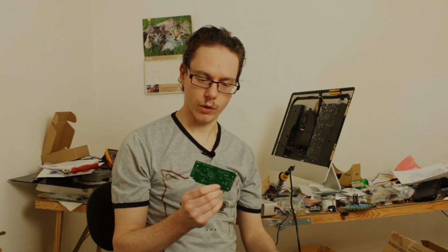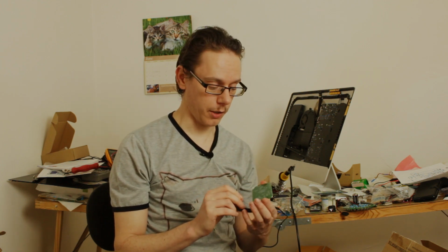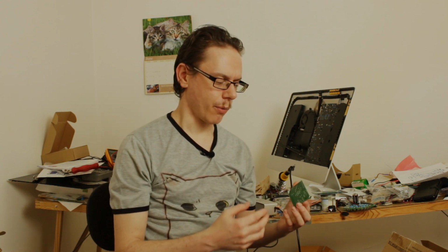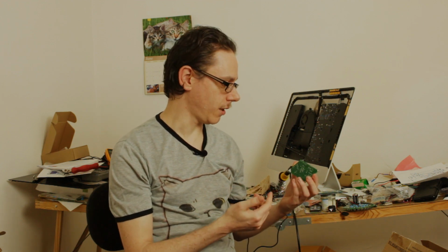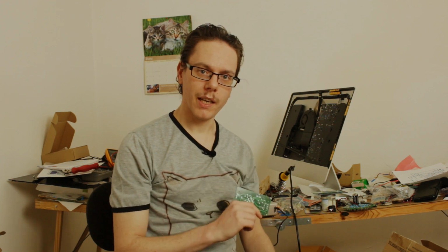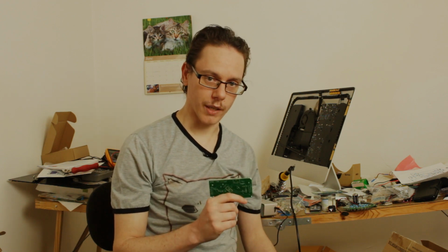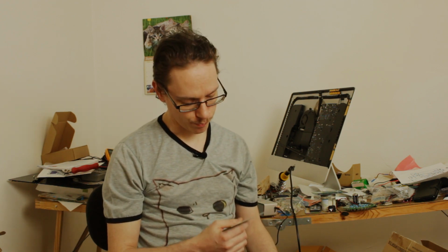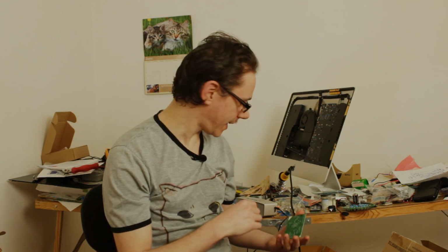So what I'd really need to do is just get a drill and just make these holes a little bit bigger. The problem with that is that then I will lose the plated through holes, because obviously these are plated through holes. And that's going to be a little bit of a problem if I'm going to drill that. But I've got plenty of these boards, so I can give that a go anyway. So let's see what I can do with that.